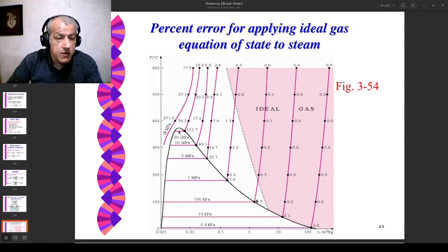Now, the other point is that if we keep the specific volume constant at 200 kilopascals, which would be somewhere here, to reach 1500 kilopascals, which would be a line here, we would have to move very far up just to reach that point. So what we expect is a very, very hot temperature at point 3 when the piston will start to lift.